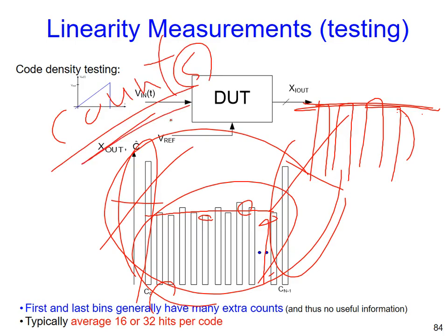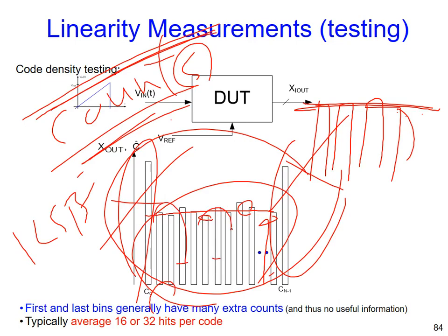So the average value, I mean the average count, the average number of times it happens, means 1 LSB. That's it. The average value. Then you can calculate each DNL, right? And after you sum up the DNL, you will get your INL. That's it. Bingo.